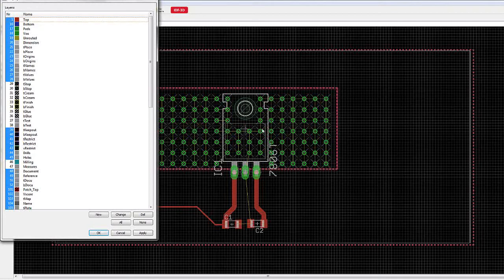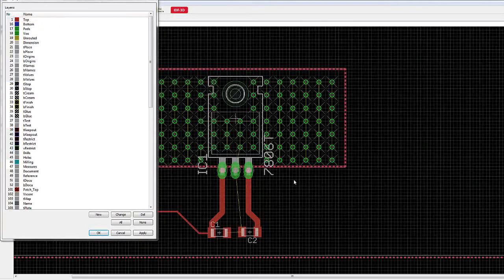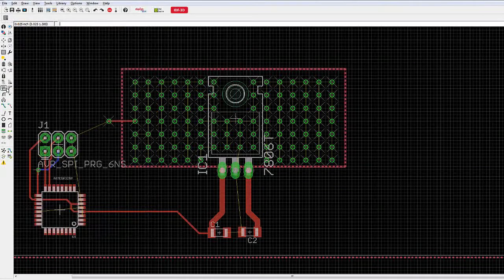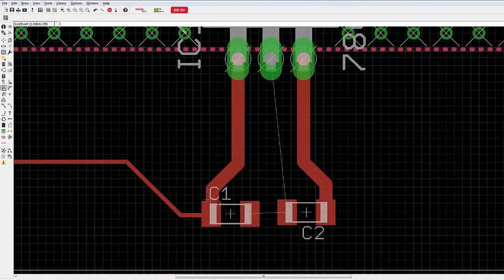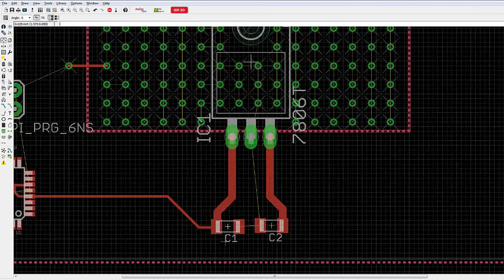Origins are for the holes. The origin layer is used to move lettering around the board. Use your smash command. Click on a component. As you can see, it puts a little cross underneath the lettering. This way you can move the lettering around and make it organized.